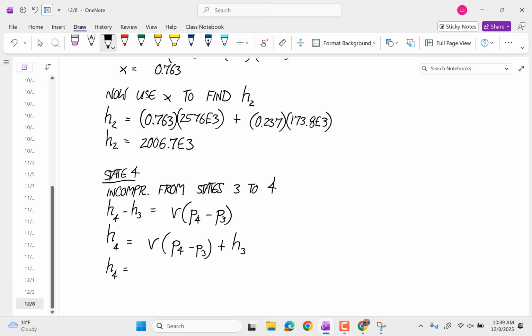Nothing matters except temperature. So for the pressure you have, treat that as the pressure in a saturated state. Make it something so that you're in that saturated state, then look at what the temperature is. And then at that temperature, you can get that specific volume.